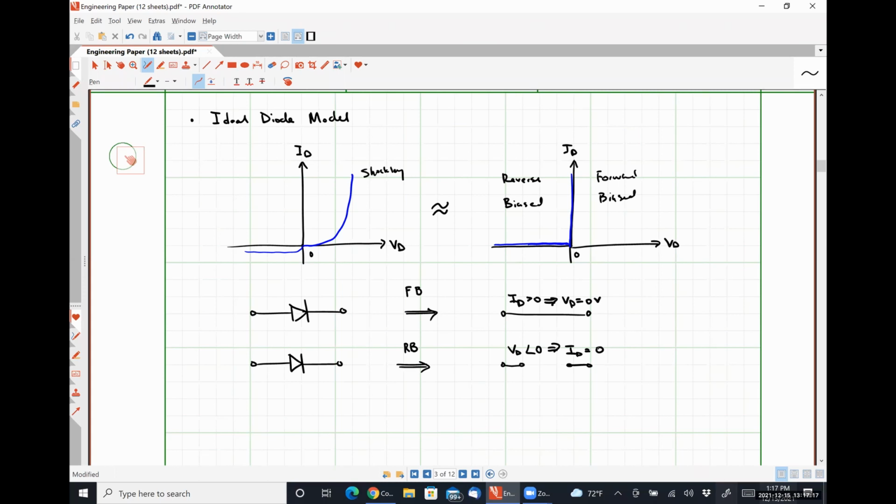And for forward bias conditions, when our voltage is more positive than a couple of thermal voltages, the current is just going to increase very rapidly. And so we are very lazily saying, let's just treat it as if as soon as the diode turns on, any amount of current that needs to flow through can flow through. Okay. So this is, again, just a quick approximation to figure out what's happening. This is a good initial estimation. It is not particularly accurate, but it is very fast to see what's happening.